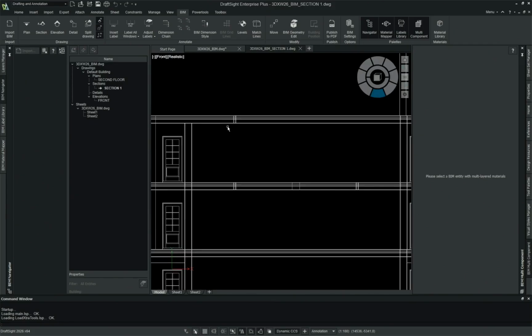In theory, I could draft on top of this as I would with any DWG file. It won't show up in the 3D model, but in the final drawing, you'll see there are extra I-beams here. You can annotate it and say, add structural I-beam, but we can't author the Revit and IFC.